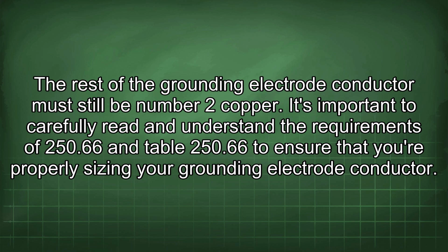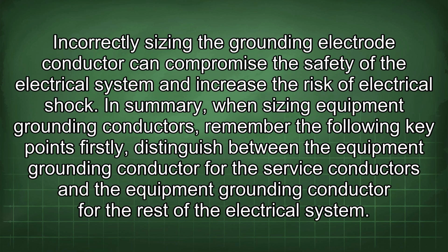It's important to carefully read and understand the requirements of 250.66 and Table 250.66 to ensure that you're properly sizing your grounding electrode conductor. Incorrectly sizing the grounding electrode conductor can compromise the safety of the electrical system and increase the risk of electrical shock.